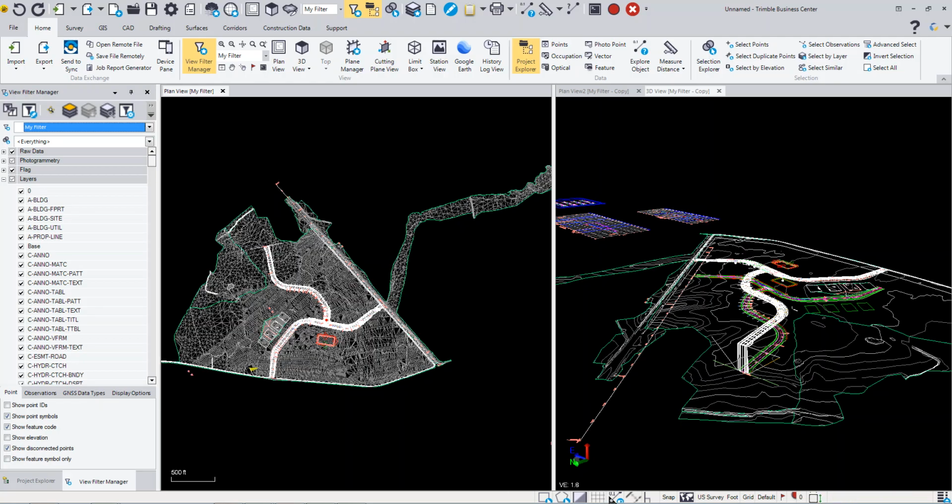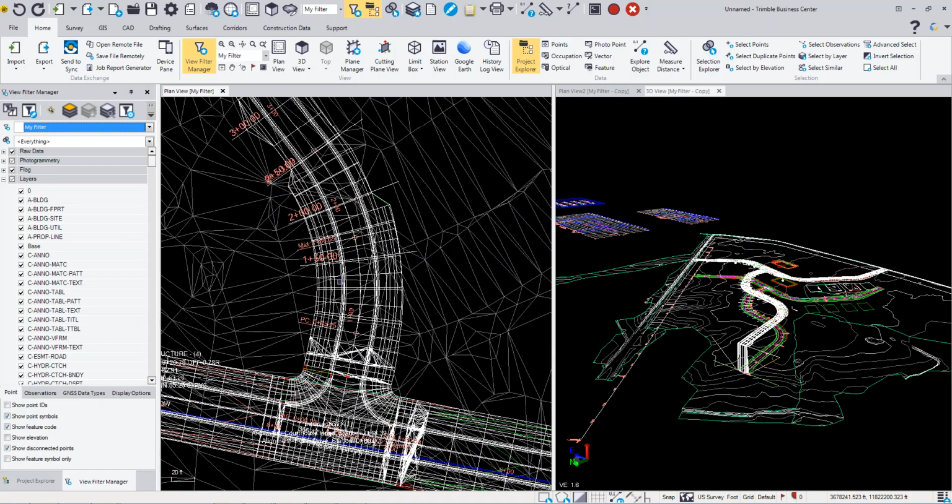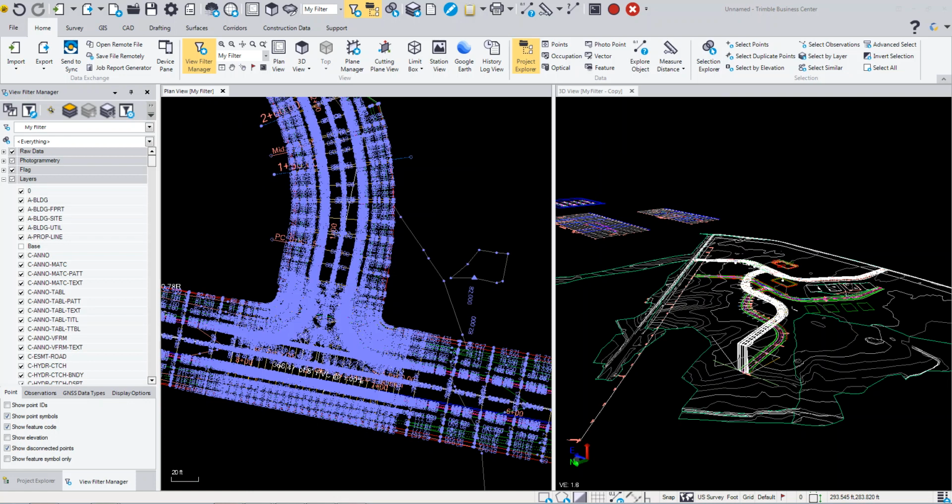The next one is the line marking toggle. If we look close down here, actually it's toggled off. If I toggle it back on, what it's going to do is display any of the line markings, like the elevations of the lines within my view. So you can see when you toggle it on, it displays these line markings, which gives you the elevations and the markings along the vertices of the objects in your drawing.